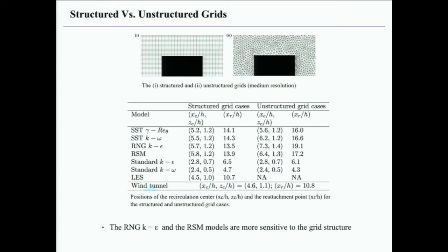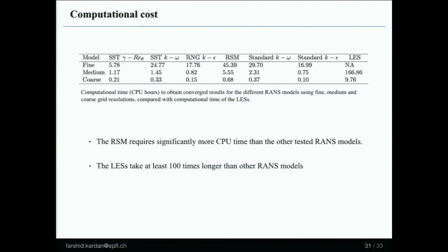And we found out that, again, these RSM and RNG models are quite sensitive to the unstructured grids that we had. I want to point out that most commercial software, for complex geometry, just puts an automatic unstructured mesh, and this could be really problematic for that.